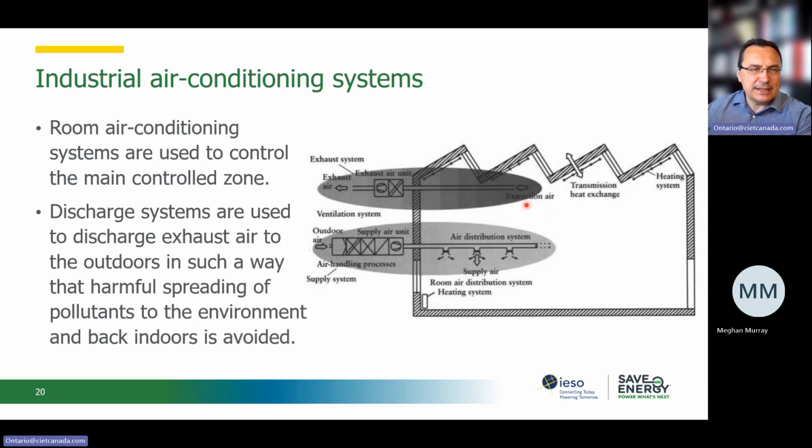So we do, in this case, address heating, cooling, filtration, see various components of the supply air systems. We also filter the air that's exhausted to maintain a certain standard for the exhaust air so that we do not transfer all that pollution outside if it's not acceptable. So we have the supply system and the discharge systems that rely on the dilution of the concentration of contaminants in the space by providing this fresh air.